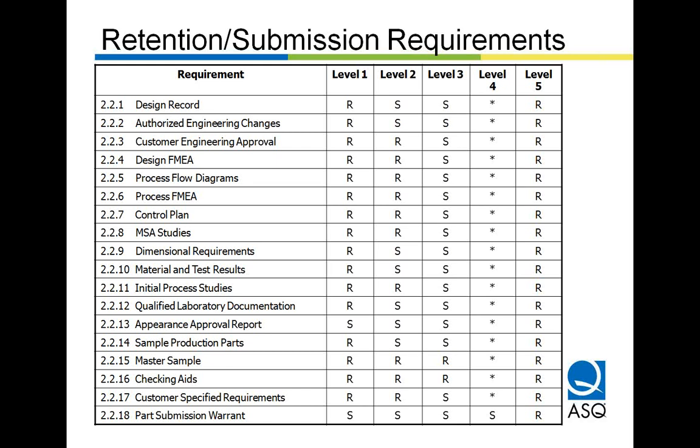What is the acceptable criteria for an interim approval of PPAP? Maybe a little vague. The criteria is that you have concurrence with your customer, that customer authorized representative, that you've identified a deficiency in the product, but you still need to ship the product.